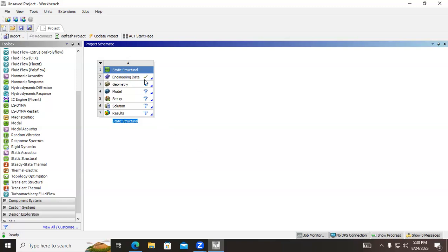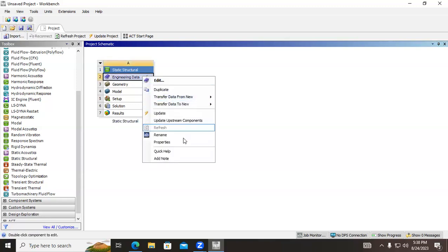All right, before we start though, we need to make one very important change for today because we are running a 2D simulation. Okay. And so by default, Ansys assumes that you're going to be running a 3D simulation, which is not a bad assumption, just because the vast majority of the time you are going to be running 3D. But for today, because it's our first Ansys activity, we are going to be running a 2D simulation.